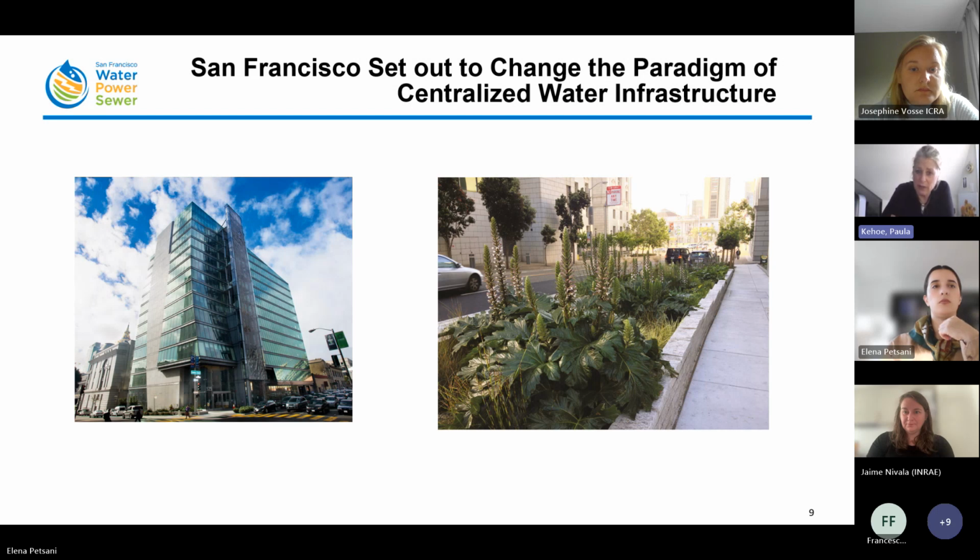And so on the outside of our building, you can see here a picture of some of the wetlands surrounding the building. This is an engineered wetland treatment system that captures the black water. Then the water goes into the basement of our building, and we disinfect that water with UV and chlorine. And then that water goes back into the building upstairs and flushes toilets and urinals within our building. We've been able to reduce our potable water consumption by over 50% with this treatment system.